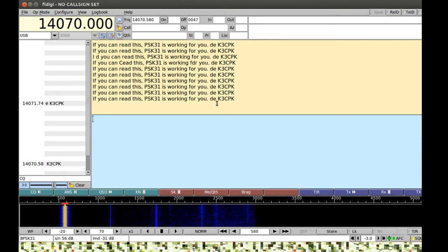Okay, and you were having trouble also? Yeah, so we've noticed our antenna. So really, because it's a 2-meter signal, your antenna should be at like this height rather than... Bigger isn't always better. Also, I could go bump up my power if you really want. On the other hand, you could bump up your LNA gain. No, that's just moving your noise floor.